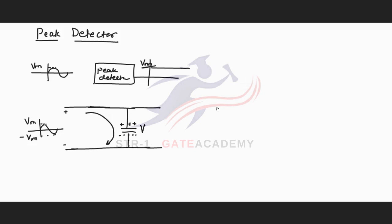And when the input reaches its maximum value Vm, the capacitor charges to a voltage equal to Vm. Now when the input falls below its peak value, suppose the input is Vm minus 1 volt, for this diode, at its cathode the voltage is Vm and at its anode the voltage is Vm minus 1 volt, meaning the cathode voltage is greater than the anode voltage.